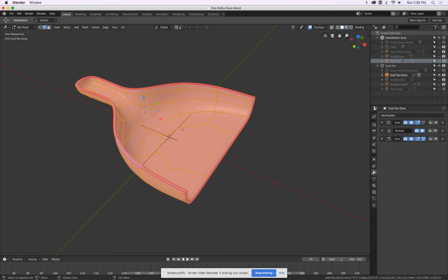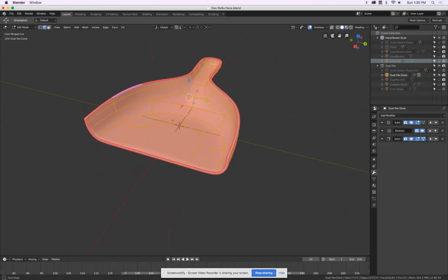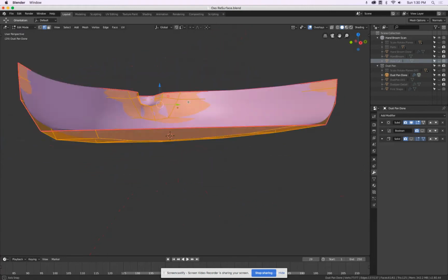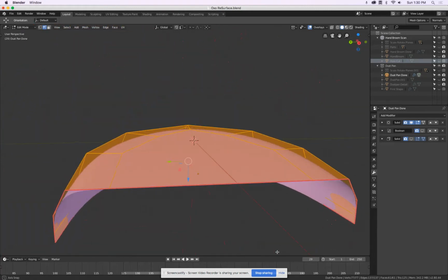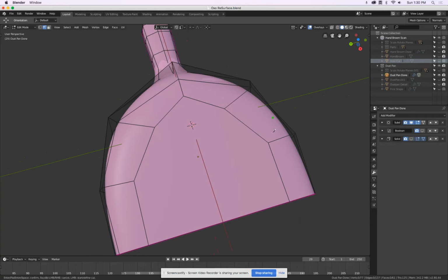Shift H, I only want to see the dustpan and turn this off and this off. I go from the underside. Very good. A A, press K, and then I see it snaps to this point, and I move a line to there, press Enter, and I added an edge. Press K, we do the same from there to there. Press Enter. Now K.